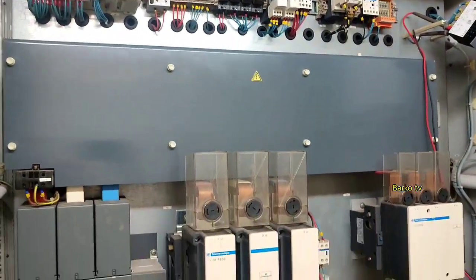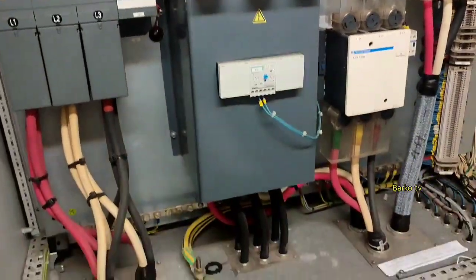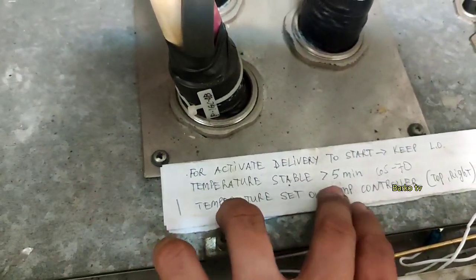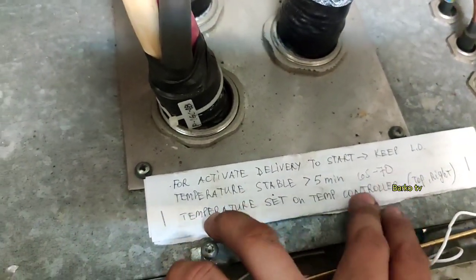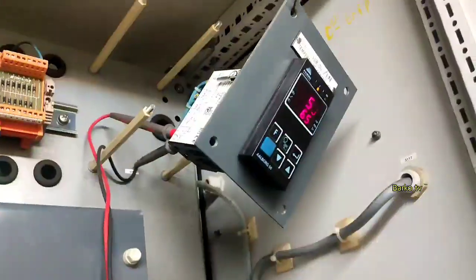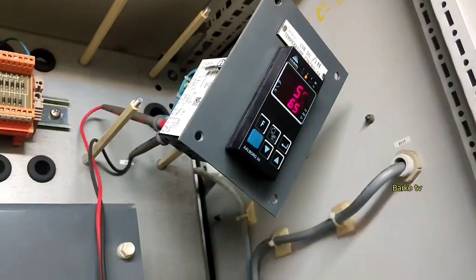Okay, so that when you start the compressor, the actuator will maintain to 70. It hits already the 65 set point, stable at 5 minutes. Okay, I hope this video helps you in your future job or future reference.